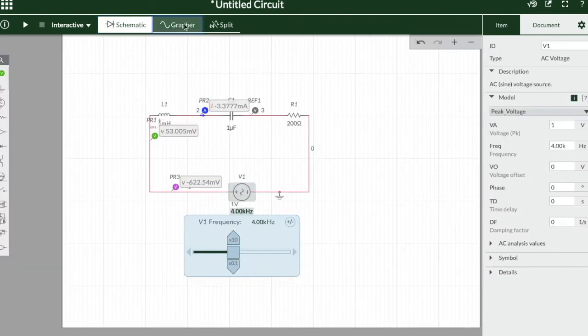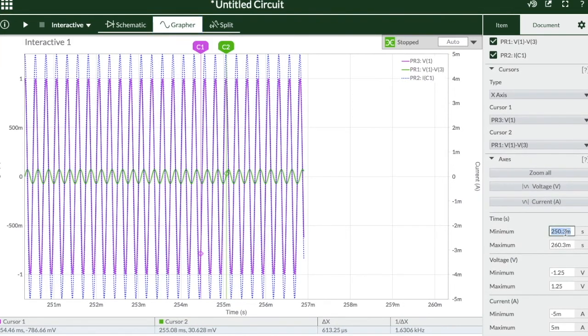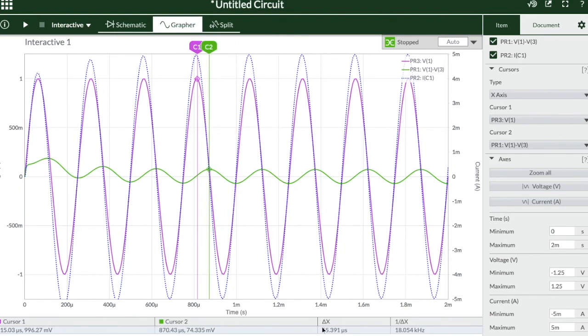When we take the frequency of 4 kHz, this phase difference now is 55.391, which is smaller than the earlier. We can observe that as we increase the frequency from a low value coming towards resonant frequency, phase difference between VLC and Vs decreases, where Vs is leading the VLC.